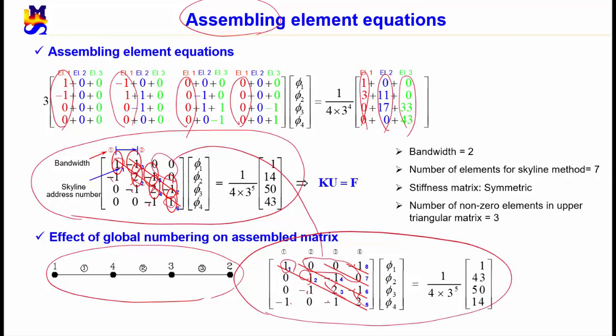Anyway, you'd better know common knowledge about some basic techniques. In this case, all zero elements are placed in the corners apart from the diagonal terms, and thus a banded matrix technique may be employed. In the banded matrix technique, the number of arrays needed is dependent on bandwidth of the matrix. That is, a maximum order for diagonal band involving non-zero element, when the order is calculated from the diagonal of this matrix. Okay, in this case, order 1 is the diagonal itself, and 2 for this diagonal band. Therefore, the bandwidth of this matrix is 2. It's just one conventional method to save the stiffness matrix.